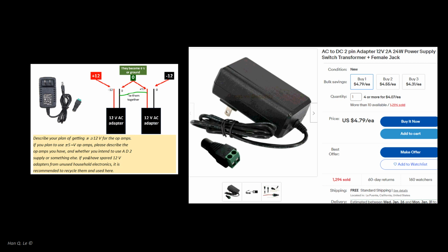Using the BK power supply has the risk of accidental touching of the knob, or incorrect setting. Sometimes, a user connects an off-state BK power supply to the breadboard and flips the power switch without checking the voltage knob settings. If the settings have excessive voltages, like 25 volt left by the previous user, damages to the op-amp will happen, and did happen in the lab. Fixed 12-volt supplies have less risk.